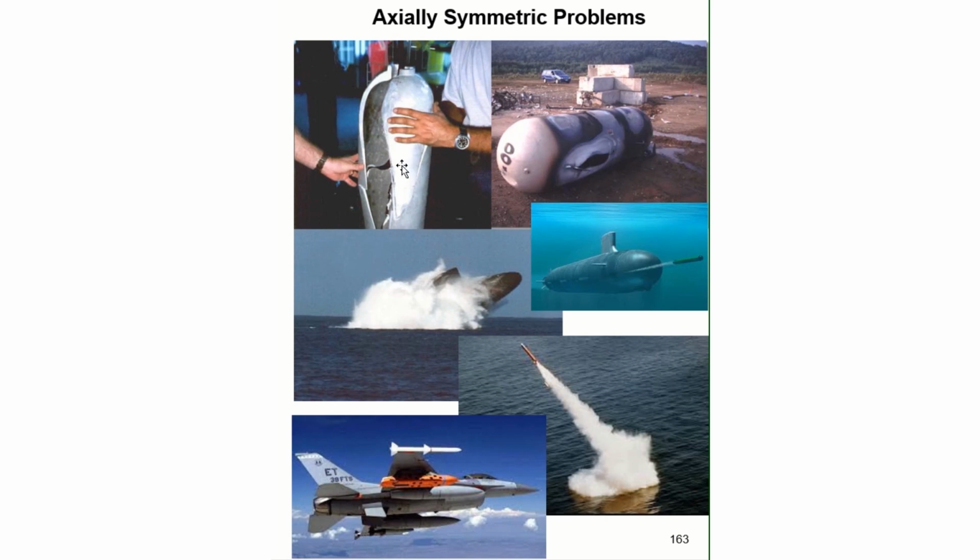The stresses that cause these failures are called the circumferential stress, and they tend to open up the crack in this direction. For thin-walled pressure vessels like these, this circumferential stress is twice the radial stress. So when pressure vessels fail, they will always fail with a longitudinal crack like this that has been generated by a sigma theta, or a circumferential stress.